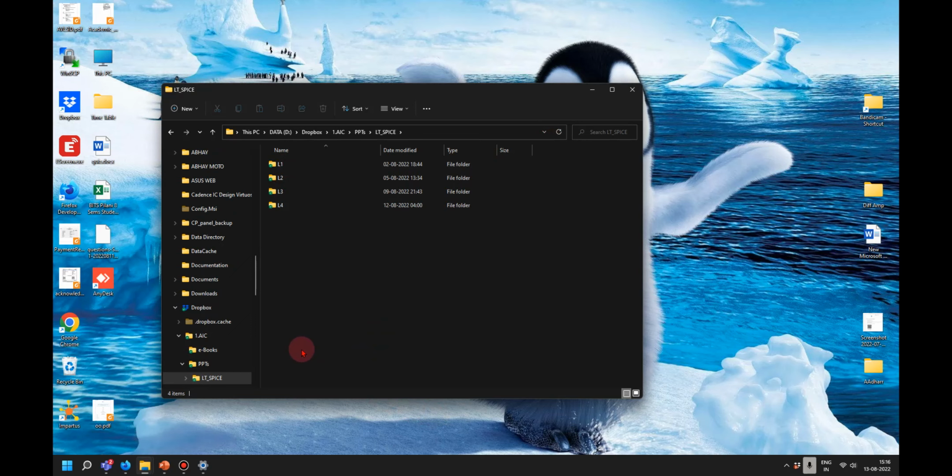It depends on circuit to circuit. Suppose there is a requirement from the circuit that the common mode signal can go from this level to this level. When a parameter of a differential amplifier is decided by the user, he would say, I want this differential amplifier to operate linearly within this common mode range. So that becomes one of the input design criteria.